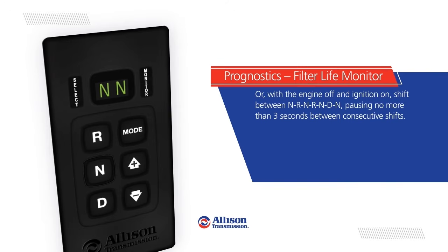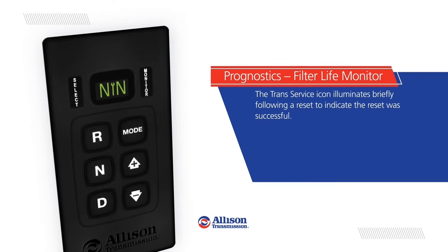Or, with the engine off and ignition on, shift between neutral, reverse, neutral, reverse, neutral, drive, neutral, pausing no more than 3 seconds between consecutive shifts. The trans service icon illuminates briefly following a reset to indicate the reset was successful.